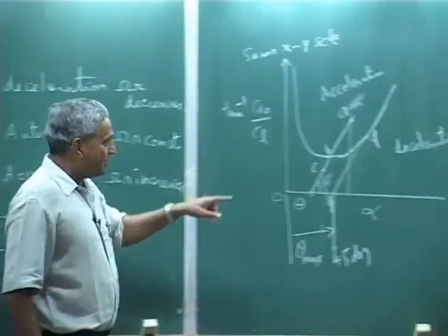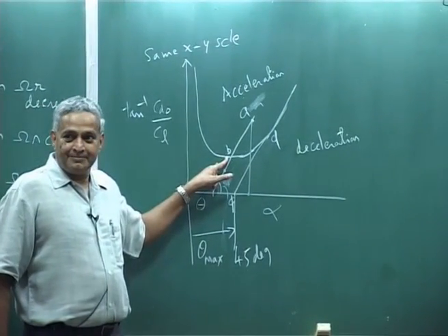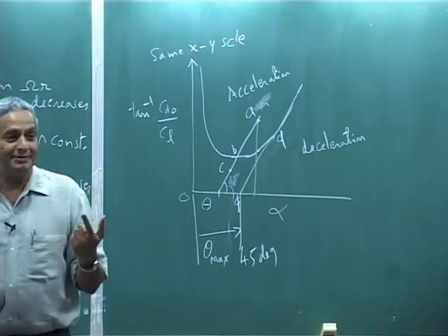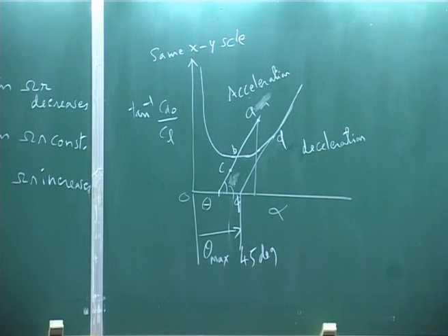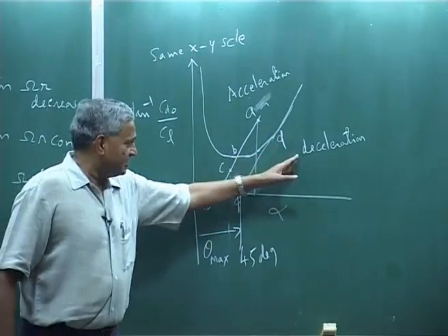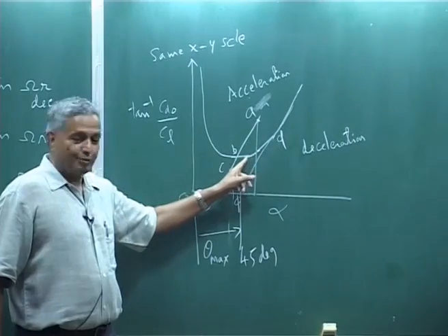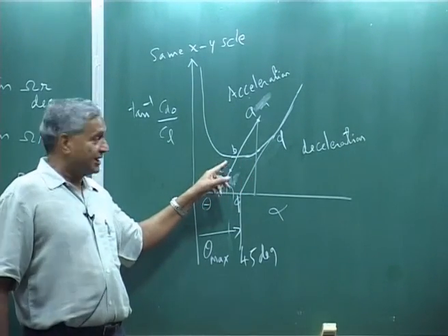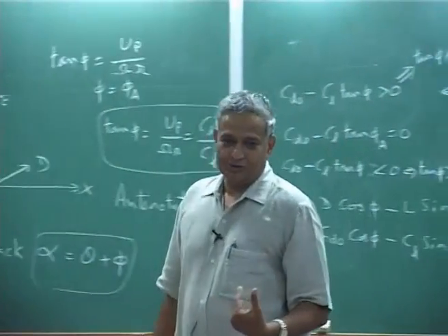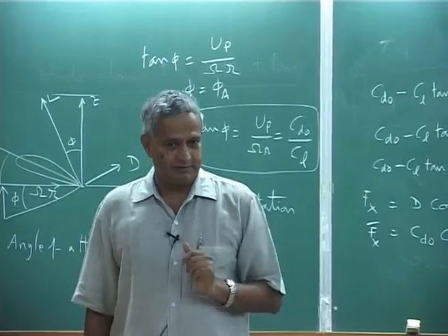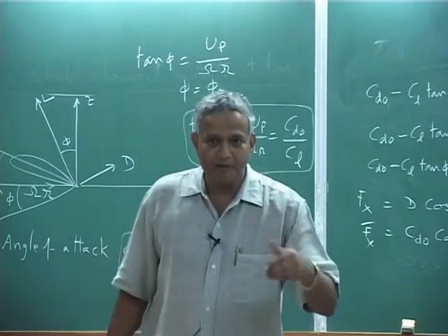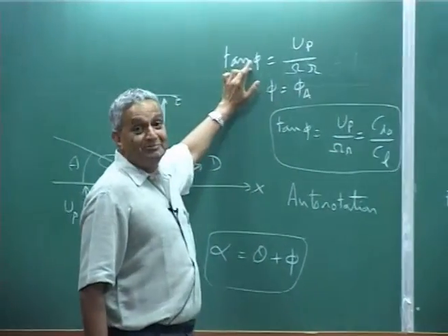Minimum means the minimum point on this curve is the point where you will have maximum omega r. So, if you decrease your collective from this point or anywhere, what will happen? Omega r will increase, but if you decrease further, again that will start decreasing. So, you will have a maximum omega r, that is the rotational velocity, only at the point where this is the minimum.